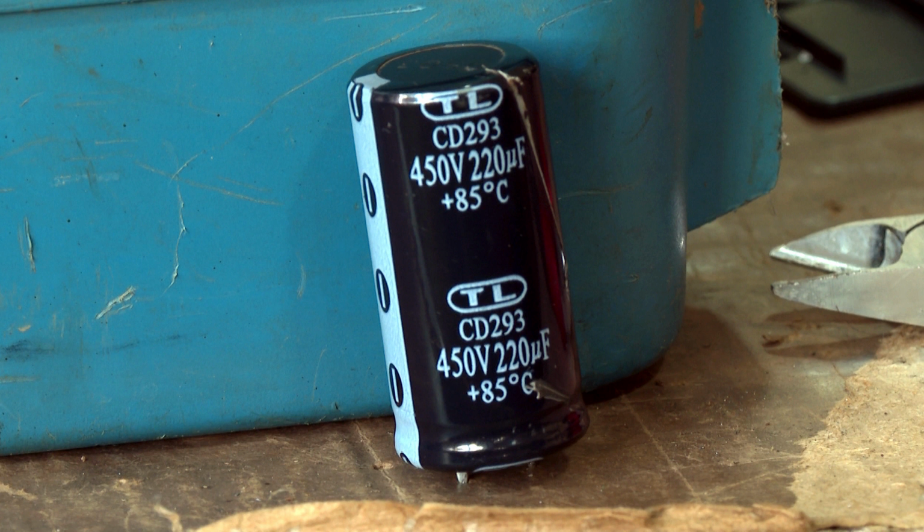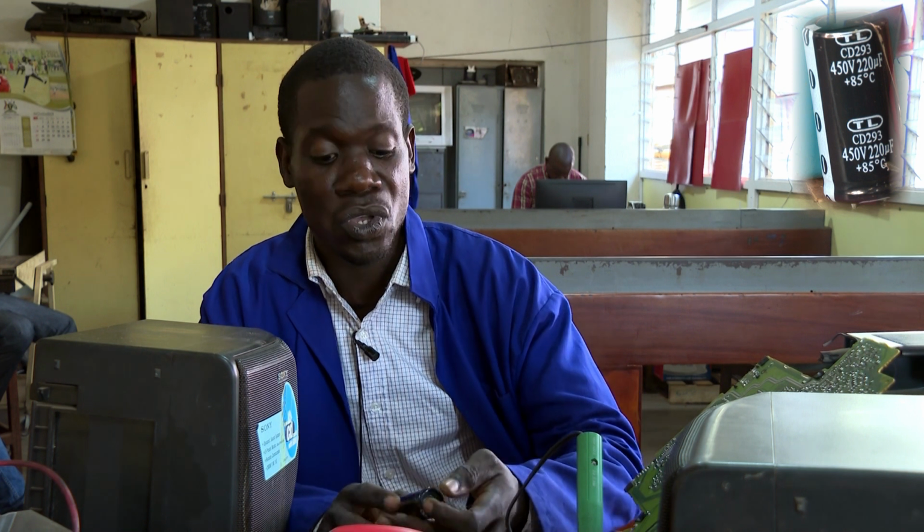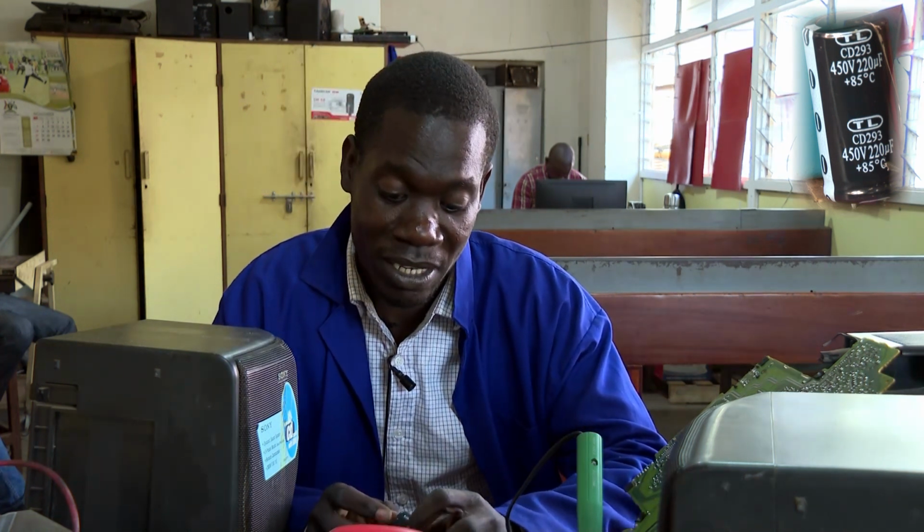But now in our capacitors we have two parts. How do you see which leg is which? One leg is positive and the other one is negative. There is a part having something like a white strip. That's the leg which is negatively charged. Then we have the part which has nothing, it has no strip. That's the positively charged terminal. So you have to know these capacitors very well.